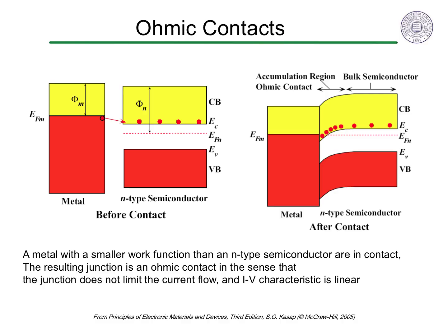P-type semiconductors also work similarly, where metals with low Fermi level, high work function, below the valence band edge should make ohmic P-type contacts. In practice, charged interfacial defect states may pin the metal's Fermi level somewhere else, making it challenging to create ohmic contacts without changing processing conditions that affect the interface structure, chemistry, and impurities.